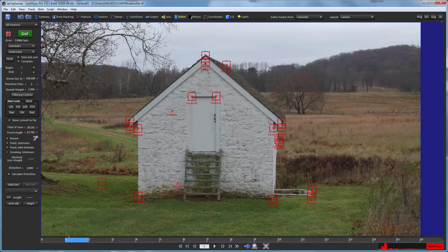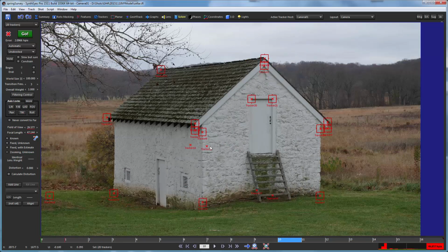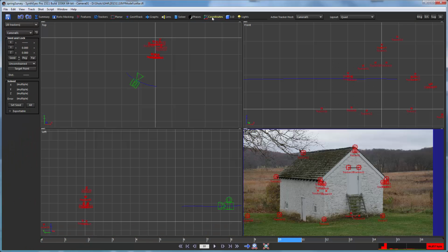It's not a flat piece of ground. So what actually is useful to look at is this roof line. Because if there's anything that's probably pretty flat and well rectified to the geometry of the building, that would be it. And those are parts that we can see. So we're going to set up the coordinate system using those particular points.